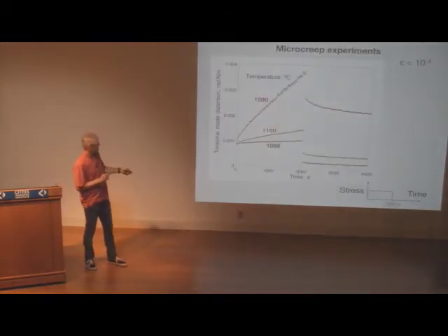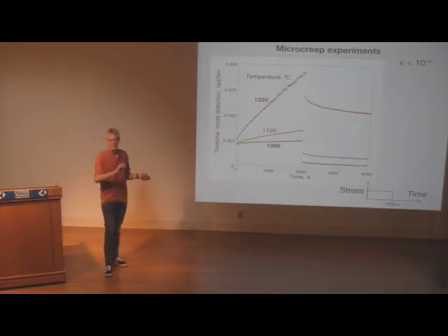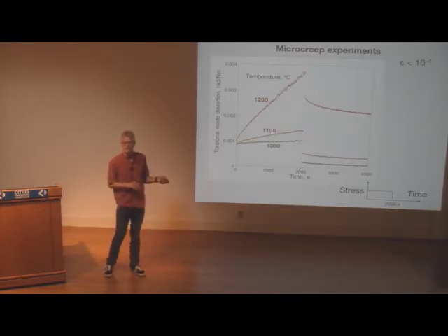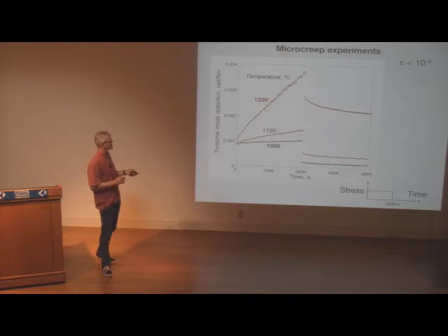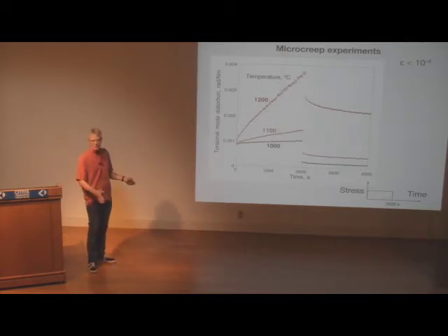So this is basically what you see here, right? You can decompose these curves into an initial instantaneous elastic part, right? That's your spring constant here. Then you can see that the strain rate changes, right? That's your anelastic part where your strain rate changes. And then at some point, you're sitting out here and you just continuously viscously deforming it, right? And that's your dashpot.